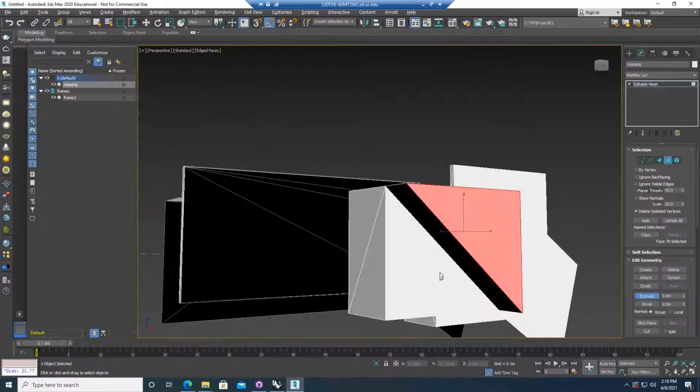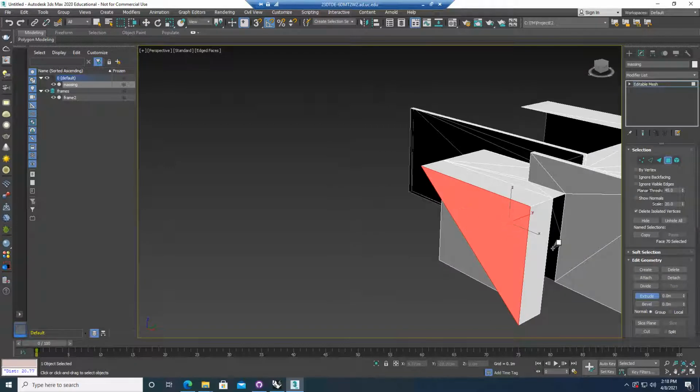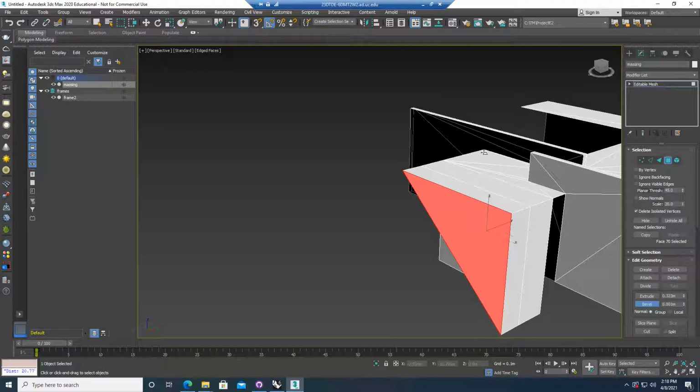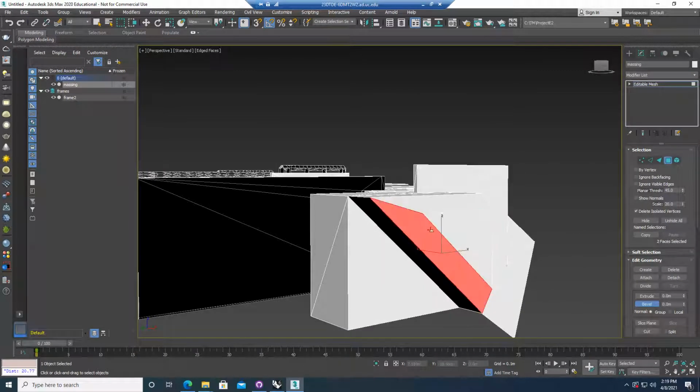Actually, all the edges here, right? So in a lot of freeform modeling, this is the basic function. You can create a really complicated form just by extruding the original form. You can also do the bevel, which is very similar to extrude. So extrude first, then if you move your mouse again, it basically allows you to bevel the edges. This could be really powerful if you are doing furniture design and you want these edges to be smooth. You can do a bevel.